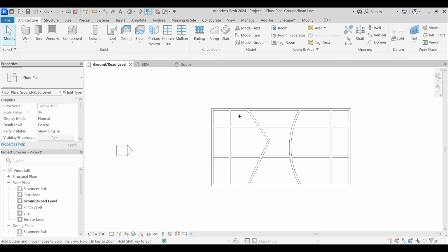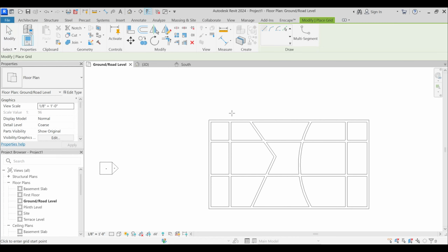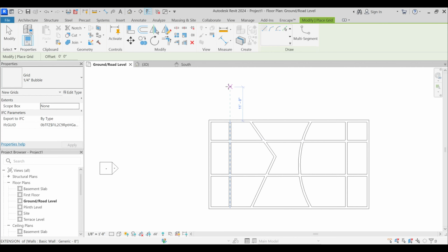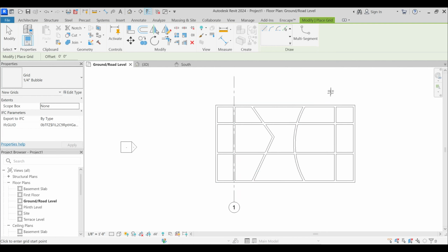And with that, now I will say that GR is the shortcut, or you can access it from here also. Fine. So I will just click GR, and from here, you see how powerful Revit is, that automatically when you hover your mouse, you see that it snaps to the center. Fine. And it snaps to the location line. Fine.